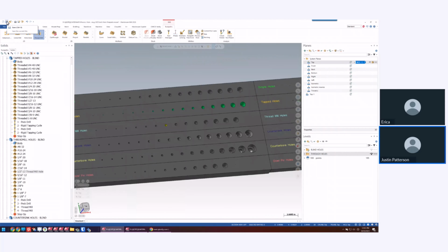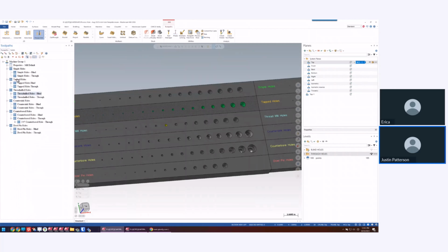So this is what's called your template. I built this template based on that type of hole. So in the example of the thread mill hole, that's a half 13 thread milled hole that's in a blind section. To do it right, I group them like this. It's the 3/4. So obviously I'd want to create another group here to call this the half 13. But it doesn't really matter. This is more organization for you. The process hole function will not care, you could have all these in one complete order. It doesn't matter. I just say do this for your organization.